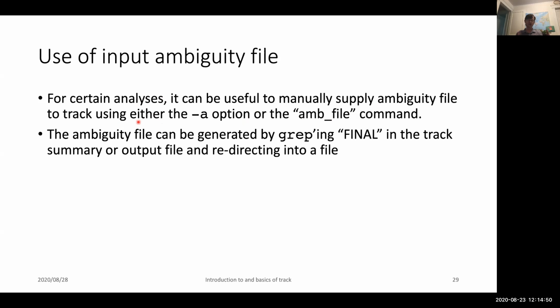For some large earthquakes, a base station which is not affected by the earthquake needs to be far away, often several hundred kilometers from the site. And since most of the time the site is a static site, we will run track with zero process noise on the site position, except for a few minutes around the time of the earthquake. In that solution, with static site coordinates most of the time, the ambiguities are more likely to be resolved to integers. So we'll run that solution and then use that ambiguity set as the input to a run of track where we now have process noise turned on for the whole span of the data.